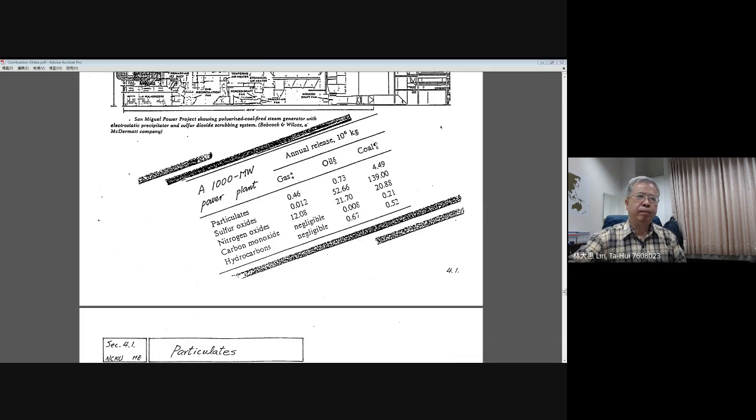And if you consider carbon monoxide and unburned hydrocarbons, for power plants we treat these two species as combustible species, which means if you do have carbon monoxide and unburned hydrocarbon emissions, the boiler does not have a good function to achieve complete combustion.